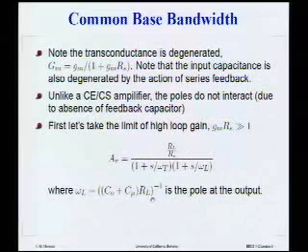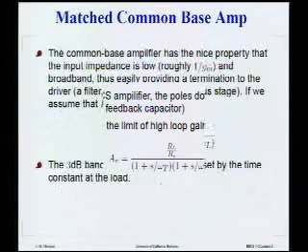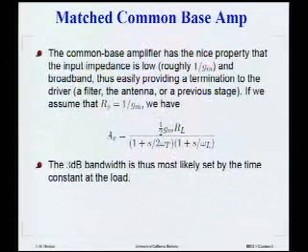These are the poles that are due to this. Omega t is the pole due to the input. Omega L is the pole due to the output. So, excuse me, I misspoke earlier by saying you have two poles at omega t. Omega L, of course, depends on the value of RL and the value of C out, whether it's loaded by another amplifier or if it's buffered. This is the same calculation, assuming that the input impedance is matched to the source impedance.